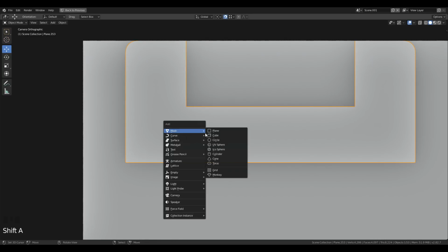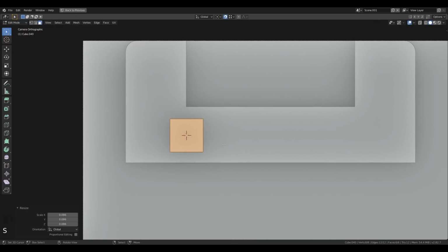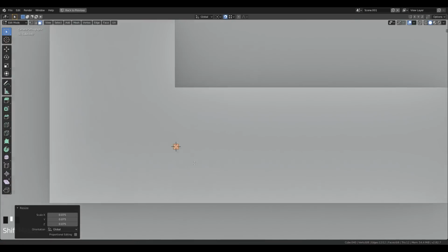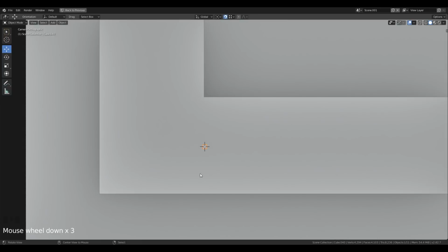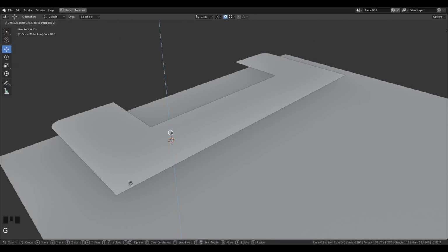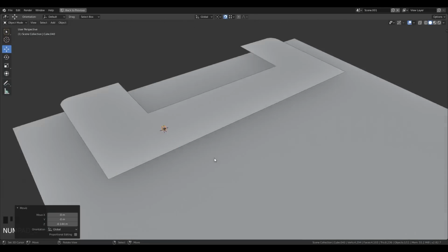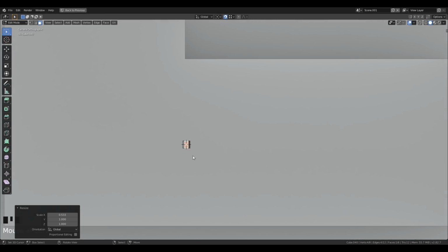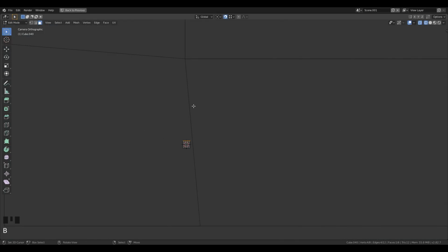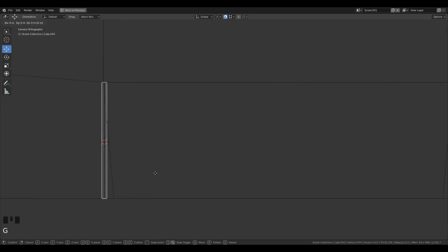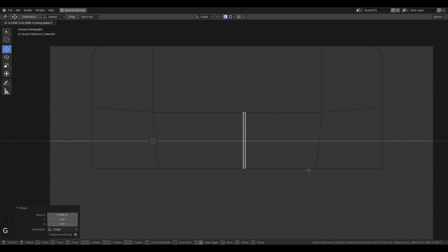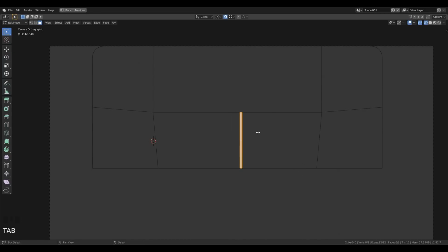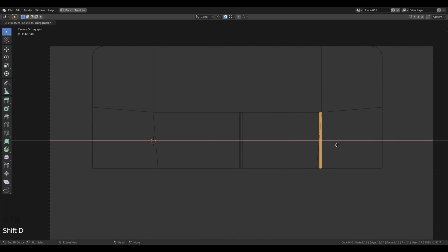To create the texture for the floor, all you need to do is add a cube to the scene and scale it down. And make sure how much depth you want to give it. And then just select the top faces of the mesh and scale it horizontally to show the sides of the mesh, which will be great to create the normals and other maps of the mesh. Then scale it vertically and use it to cover the whole area of the floor beneath it. Then just duplicate it several times to make a grid of the floor and then use the same mesh over and over again.